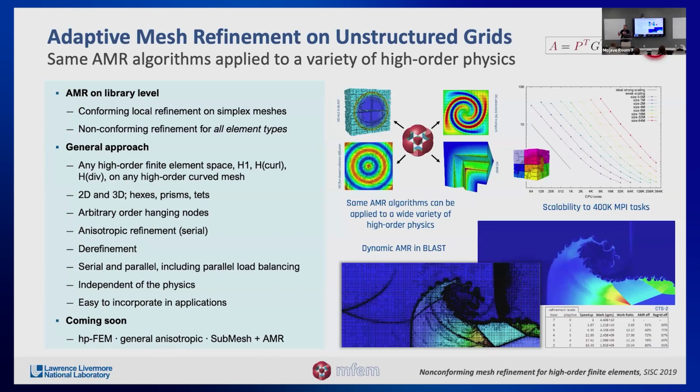Submesh is one of our capabilities where you can do multiphysics by extracting a portion of the domain. In the past, this only worked for conforming meshes. There's work now to make it work with adaptive mesh refinement. You can imagine that with AMR meshes, that is not trivial. But all three of these have a PR associated with them, and they're coming up next year.